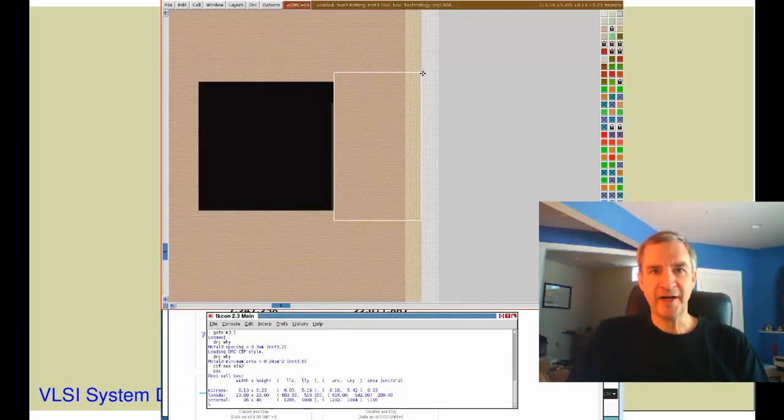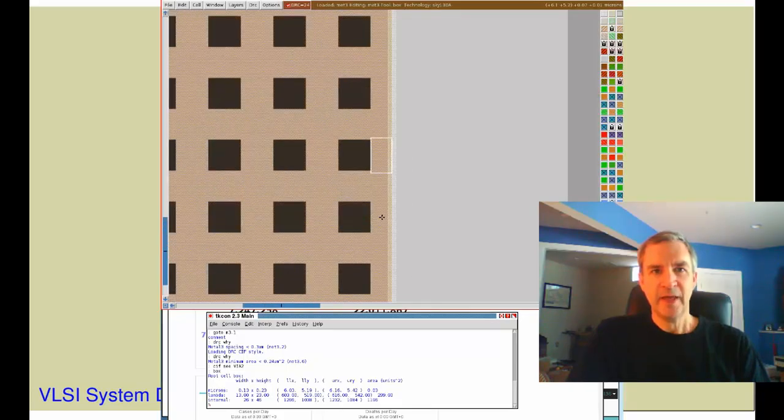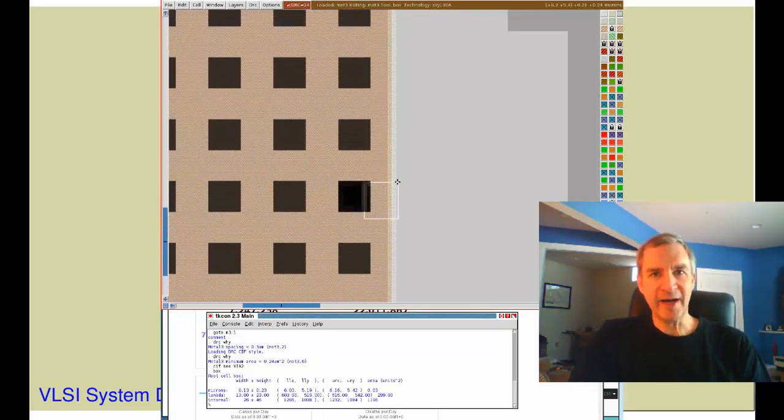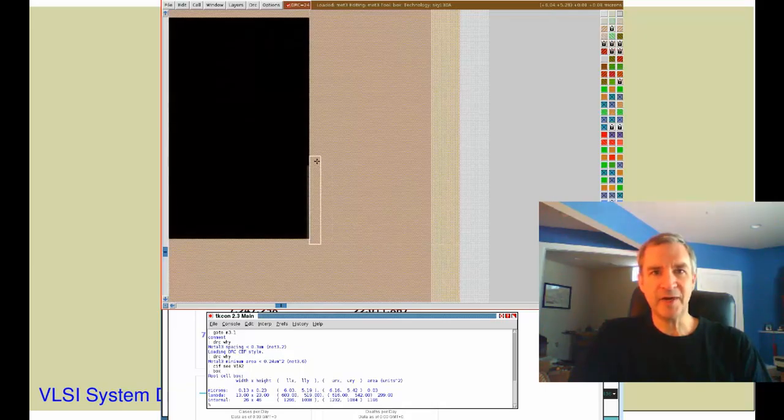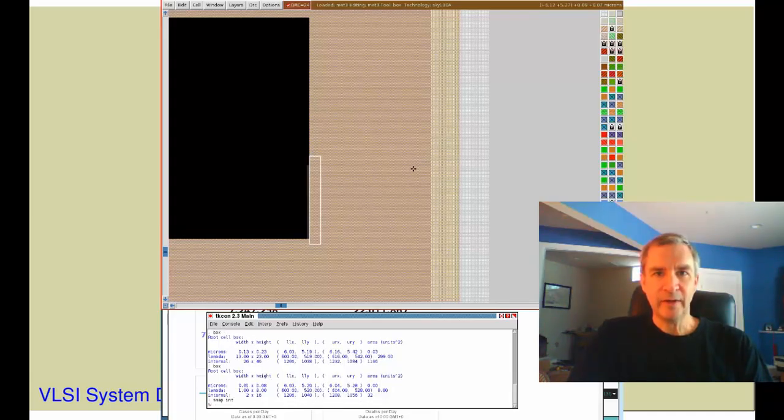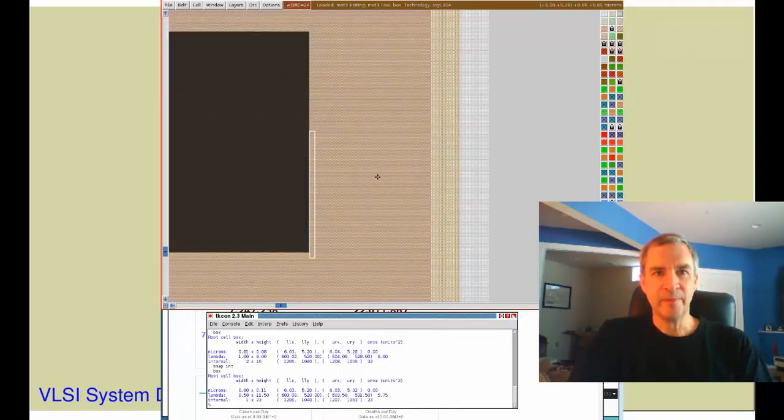This technology file is set up to work on a typical grid of 0.01 microns. This helps make a layout a bit simpler by not having to work on a 5 nanometer grid, but if you want to move the cursor box around on a 5 nanometer grid, you need to run the command snap internal or snap int. Otherwise, you may not be able to align the cursor box with the edge of the via shown in the CIF-C view.